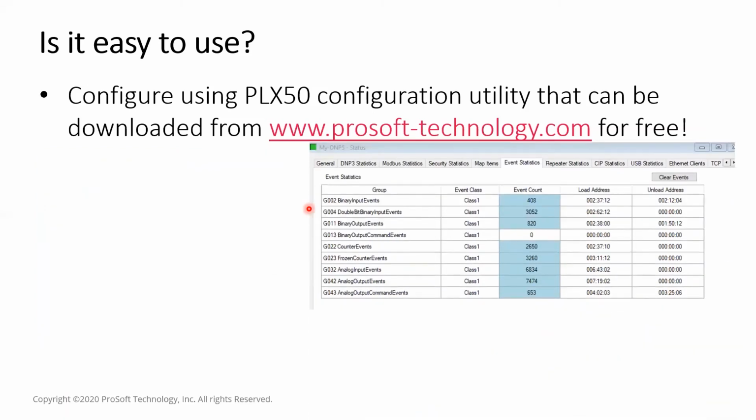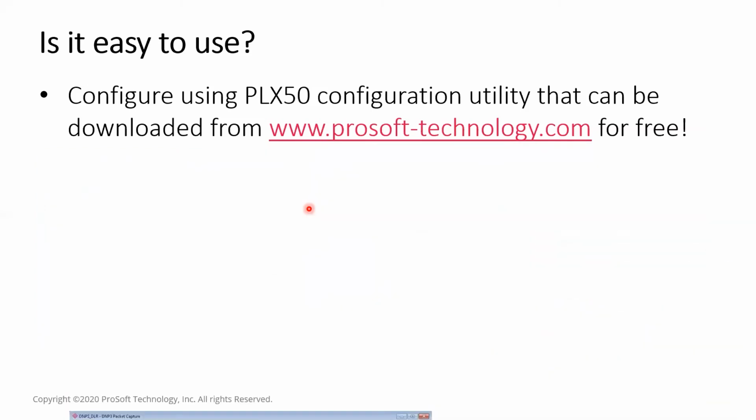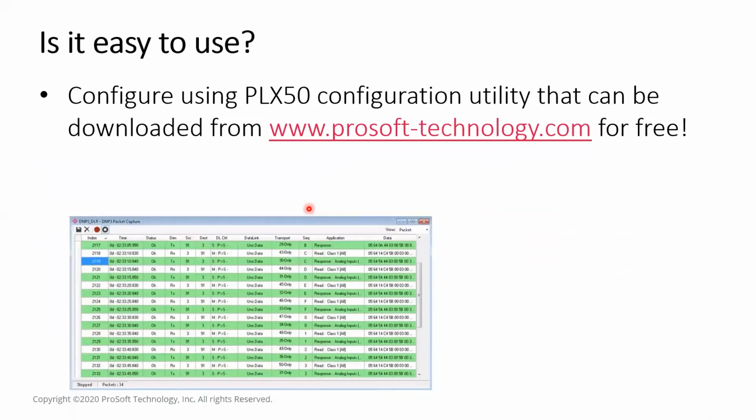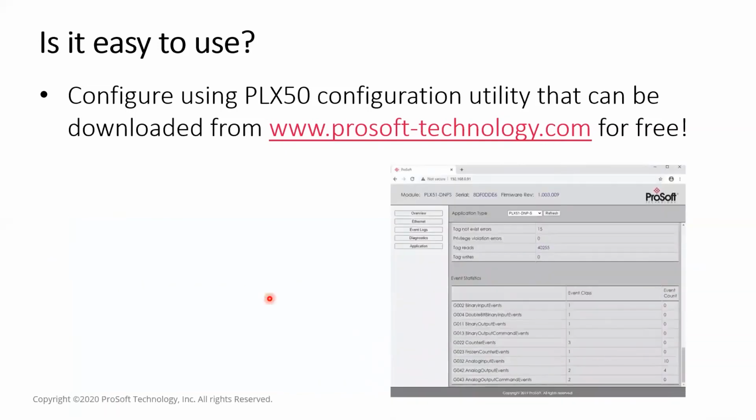And you can actually see a lot of the diagnostics features come into play. Here's a screenshot of the protocol analyzer, where you can see the bits and bytes, but you can also see that the information has been decoded to say whether it is a response, a read, or a send, who is the destination and who is the source. So you've got all of this information that helps you diagnose any problems very, very quickly. And then, of course, the web server as well.